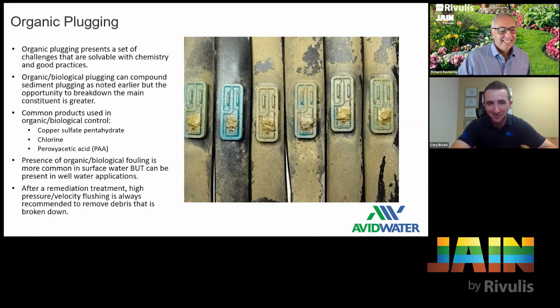Yeah, and so this photo, this is organic buildup, right? This is that sticky stuff I talked about. That isn't peanut butter. That's just bad news bears, for lack of better words. So organic plugging presents a lot of challenges, as you can see. Most of the time it's solvable with chemistry and good practices. This kind of organic biological plugging can compound the sediment that we talked about earlier, but because it's alive, it has an opportunity to be broken down or even killed, for lack of better words, in a more realistic fashion than, say, removing a piece of sand.